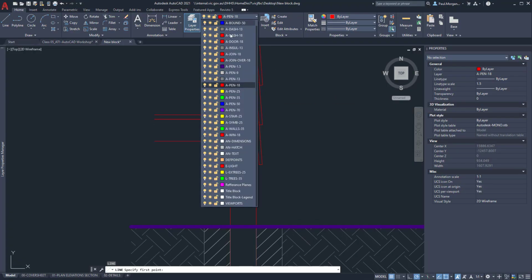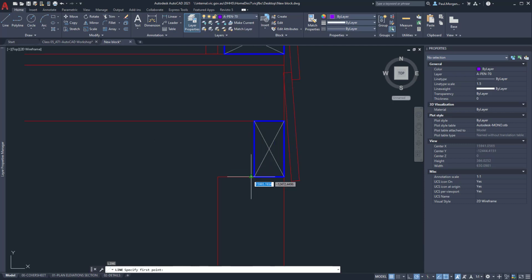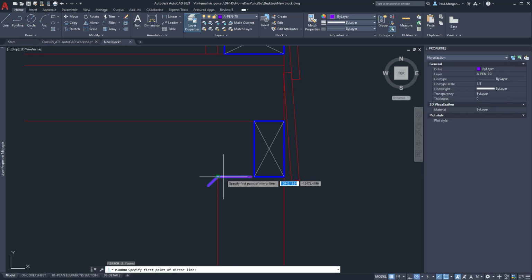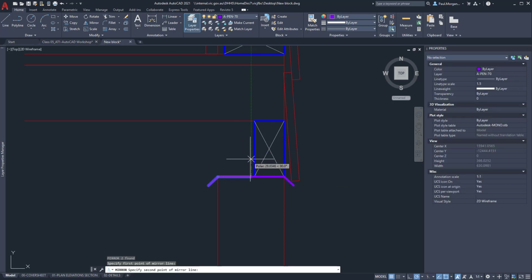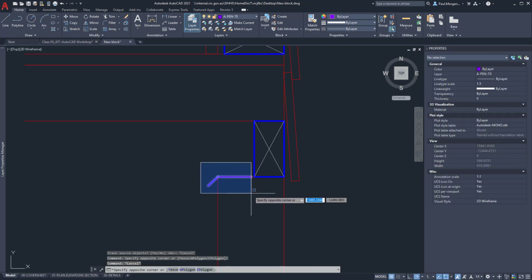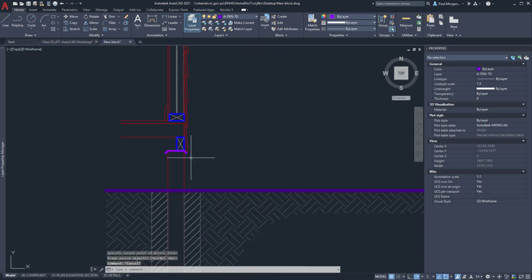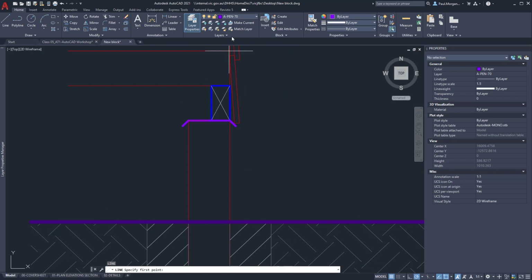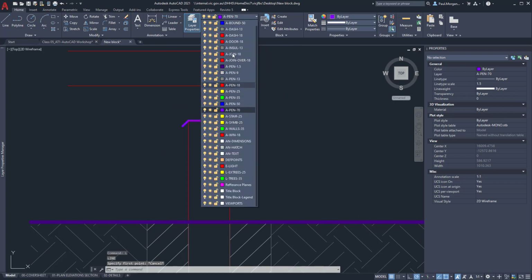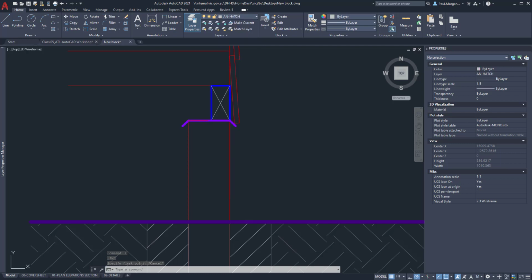So I'll come back to here, and it's really quite simple. I'm going to take a pen 70, start from the center, come out, come down, say 20 mil, hit escape, click once, click twice, mirror from the center of the stump, okay, like that.